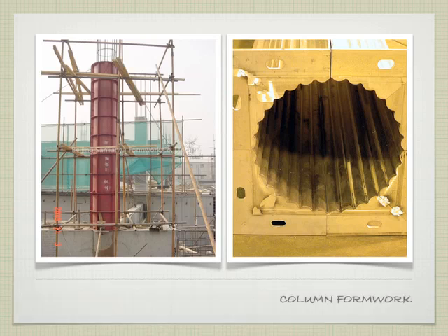So they can end up being more decorative. Obviously, something like this that's cast out of either aluminum or steel is going to be a little bit fancier and certainly something that you're going to reuse over and over again. Generally speaking, if you're using steel formwork, you're going to be able to reuse it many, many more times than you would if it was wood formwork. It could be aluminum. If you're casting against it, it doesn't make much difference.